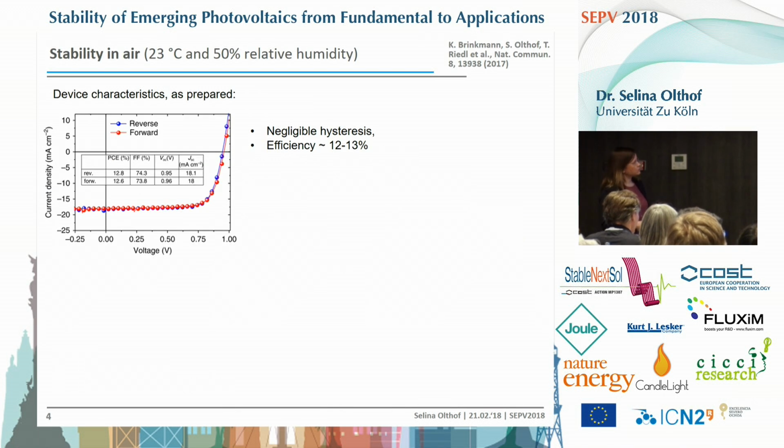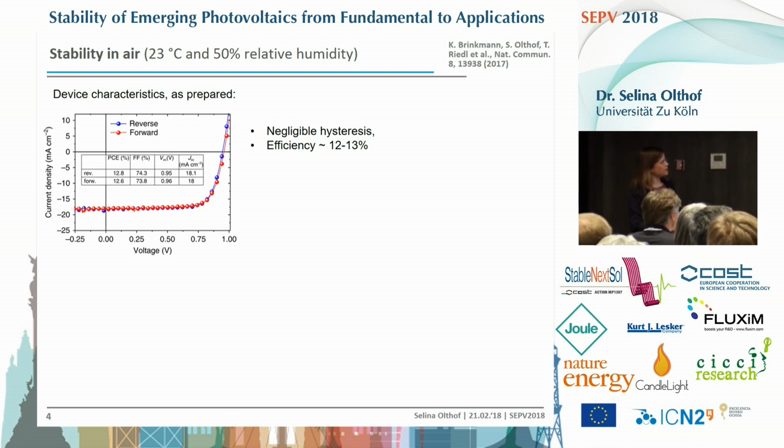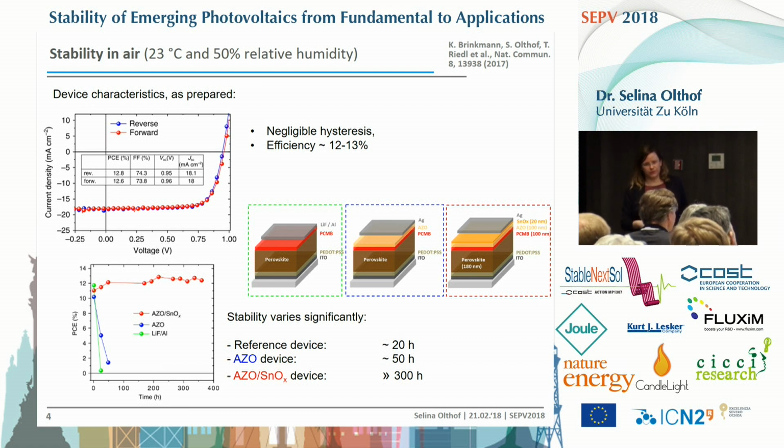This is an IV characteristic of these devices, so they all look kind of the same, independent of the device stack. We get about 12 or 13%, so it's decent efficiency for these kind of stacks, and no hysteresis, as is quite normal on these PEDOT, as we already heard. But they are very different in their stability behavior. If you look at the reference device here in green, it dies within a measurement.